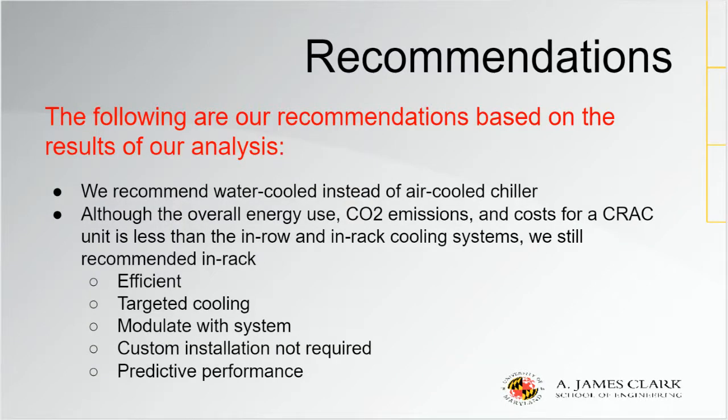To conclude the presentation, the following are the recommendations that we propose based on the results of our analysis. First of all, we recommend a water-cooled instead of an air-cooled chiller. As we saw from the results in this presentation, the water-cooled chiller is a lot more efficient. It required less energy, it produced less carbon emissions, and also it cost less in general.